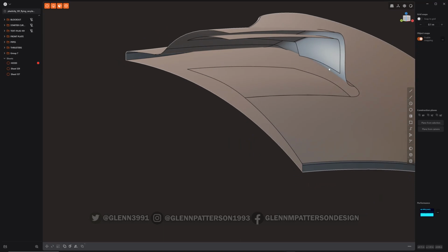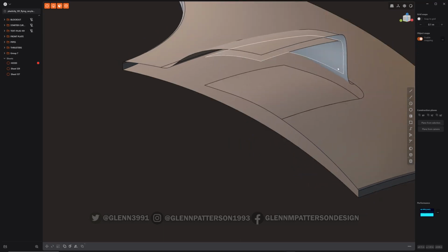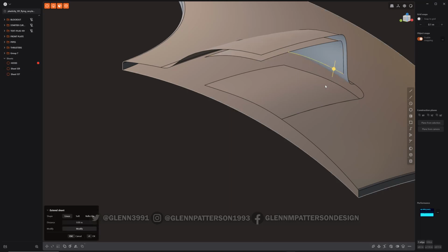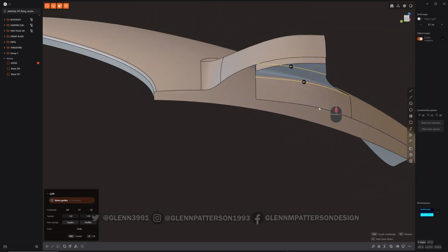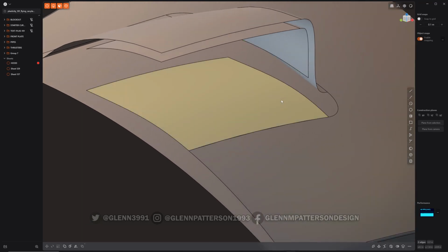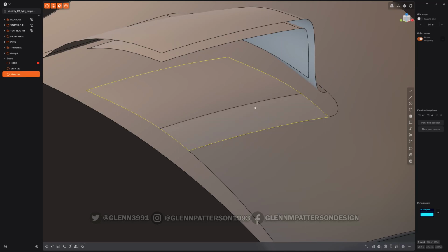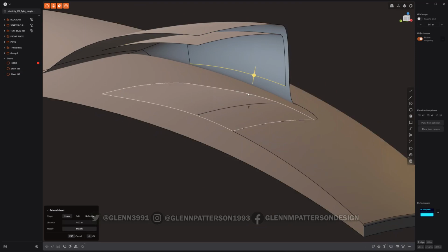Okay, cool. So now we run into the same problem again, is this edge here has to come to this edge here, and you look at loft, it does a bunch of weirdness up here, so let's go ahead and escape that. Let's fix that. Another cut here. Should be second nature by the time you're done with the end of this video.